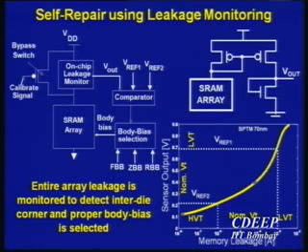By the way, some of you might be familiar with the fact that body biasing may not be very effective in scaled technologies, 45 nanometers and so on. Turns out that you can use source biasing in that case. So rather than using body biasing, one can use source biasing. What does source biasing do? It actually changes the VGS of the transistor and still gets more or less a similar kind of effect.